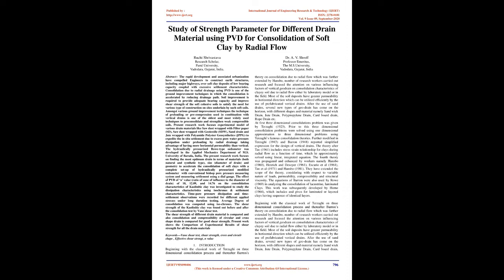The effect of PVD of N value, ratio of zone of influence to the diameter of drain, of 10, 12.09, and 14.76 on the consolidation characteristics of kaolinitic clay was investigated to study the dissipation characteristics using isochrones and settlement characteristics. Time pore pressure dissipation and time settlement observations were recorded for different applied stresses under long-duration testing. Average degree of consolidation was computed using isochrones.